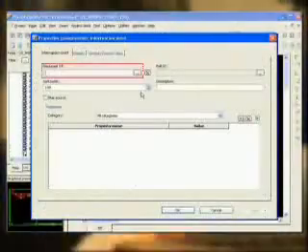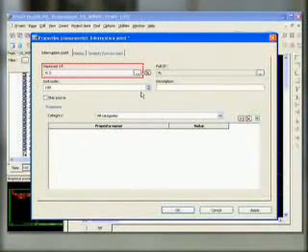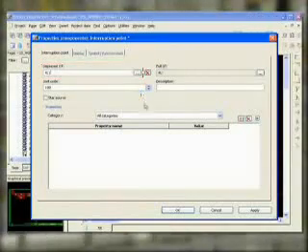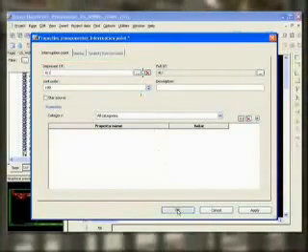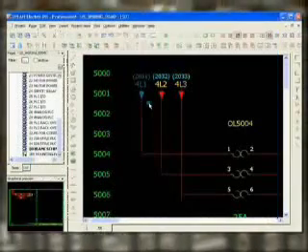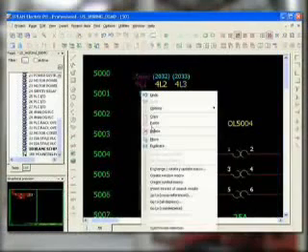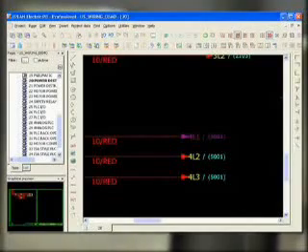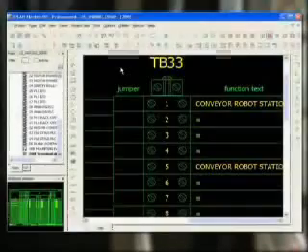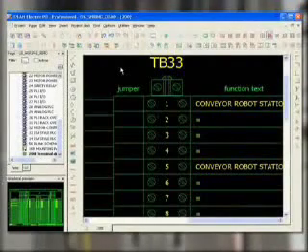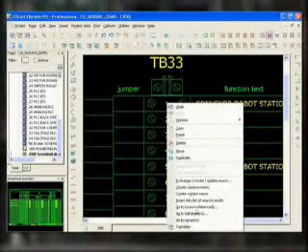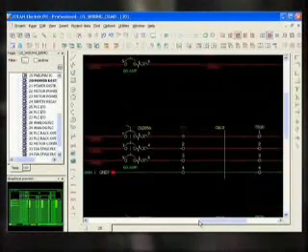You can cross-reference interruption points the same way. Simply give 2 points the same name and Eplan will link them. The reference shows up automatically. You can jump between pages by selecting Go to Counterpiece. The reference is also shown on the counterpiece. Reports also cross-reference. You can jump directly from a terminal report to the schematics by selecting Go to Graphic.